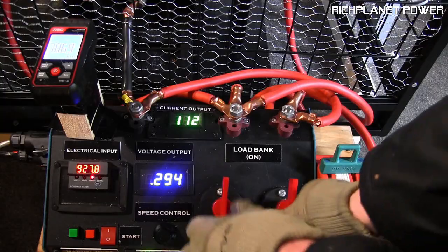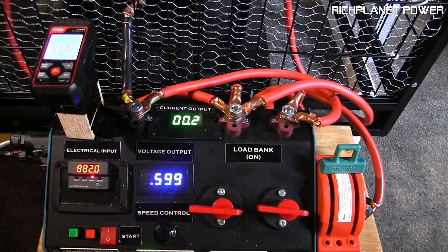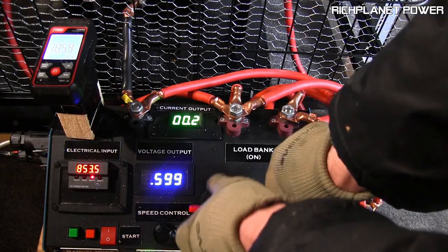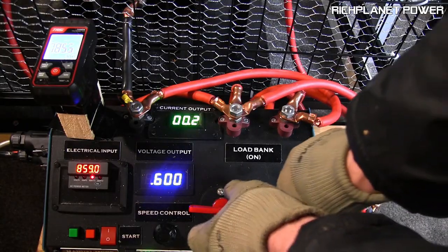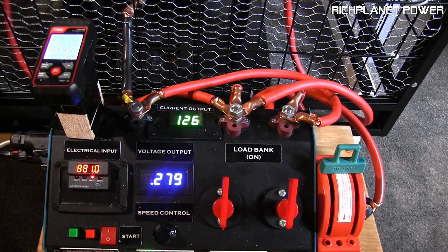Now, I managed to get some results with the machine running at 4,000 RPM, which is significantly faster than 2,900 of the previous motor. However, this proved inconclusive for a few reasons. Firstly, the input power, which should have been fairly fixed when running at a fixed load, was varying around quite a bit. This made the readings inconsistent, too inconsistent to draw any conclusions.